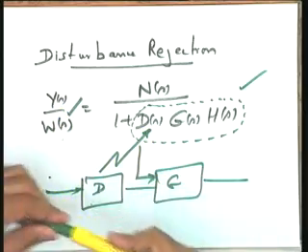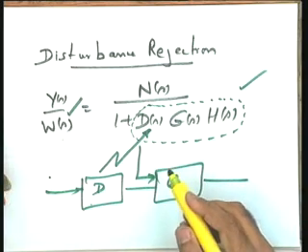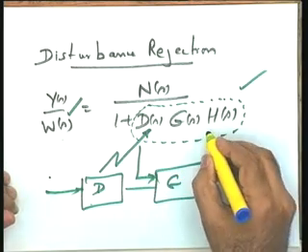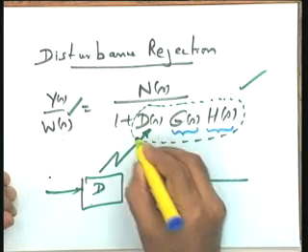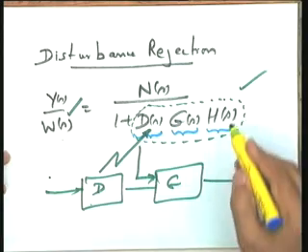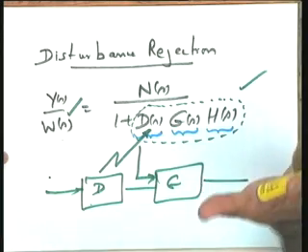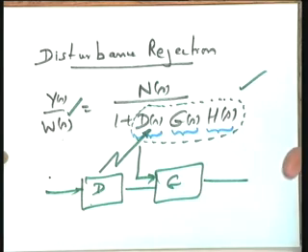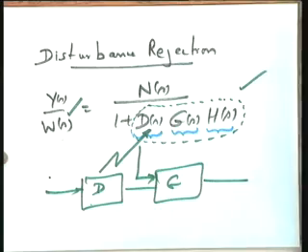Now at this point, one specific information I would like to give, that as far as the loop gain is concerned, there are three parameters, please: H(s), G(s) and D(s). I assume that H(s), the sensor, you cannot play with that sensor. You cannot increase the loop gain by increasing the gain of the sensor. Sensor itself has got certain constraints.